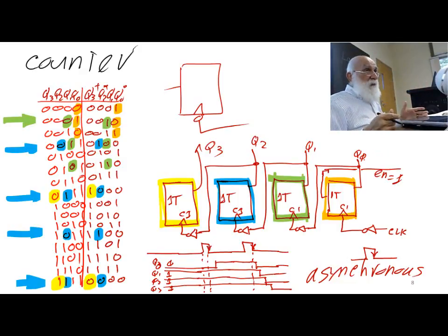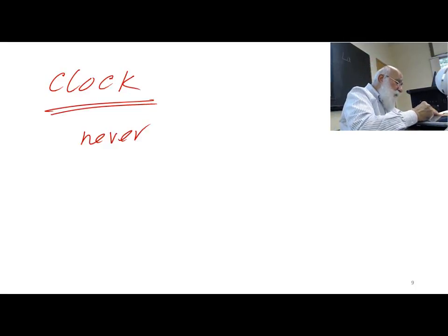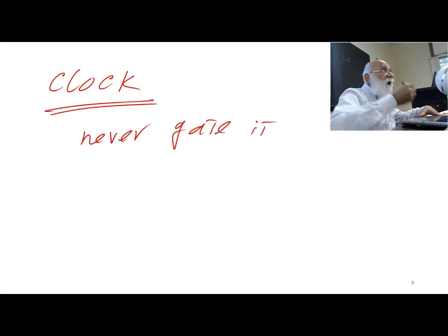For now, whatever we do, we take the clock very seriously. So let's talk about the clock. I never gate the clock. I never take an output of a flip-flop into the clock.